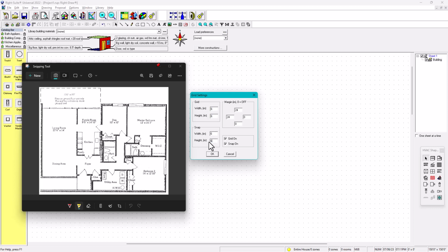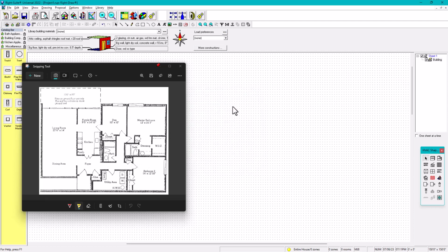Put it 6 inches, because also this is not even going to be the best accurate, because you need to consider also, see this, the thickness of the walls, right? Because when we draw it in Wrightsoft, you're drawing a line. However, the walls have thickness, right? So this is a very good approximation of the heat load. So we're going to put 6 6 6 6, or everything is 6. Okay, then it's done. See, it's 6.